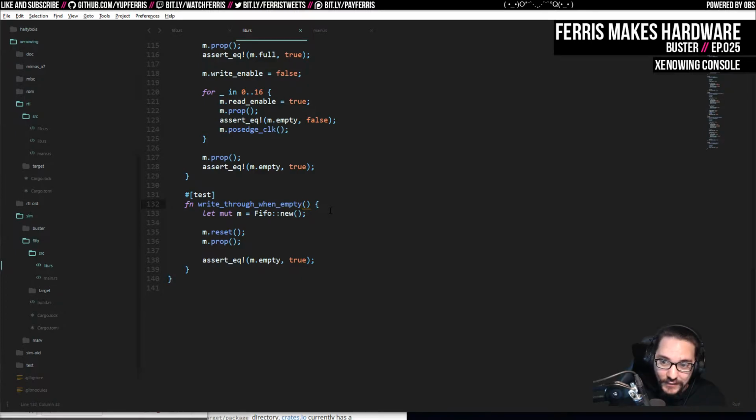Essentially, if I'm able to read through the FIFO faster, then I will get away with having fewer buffers in the bus implementation. And just like we're doing with the FIFO, where I'm pushing a bunch of data through, I'm going to write the same kind of tests for the buses, where I do a bunch of dummy reads and writes through the buses and make sure data gets where it should have gone.